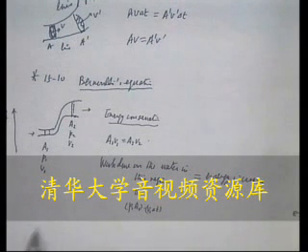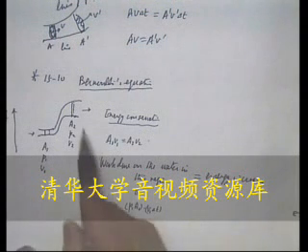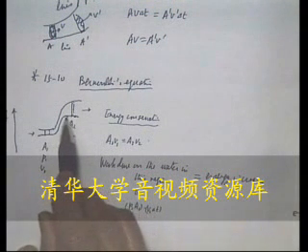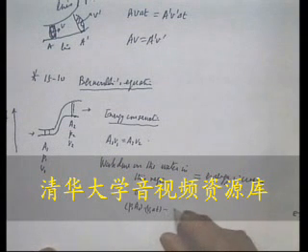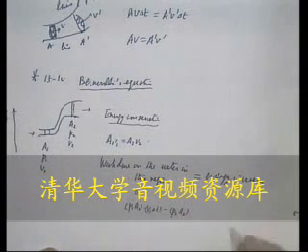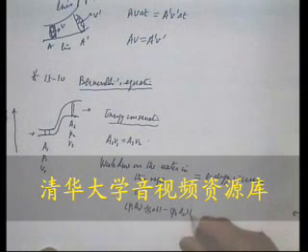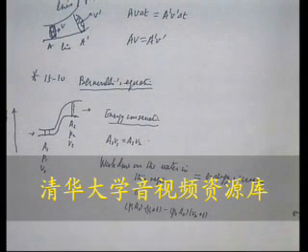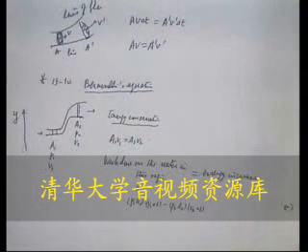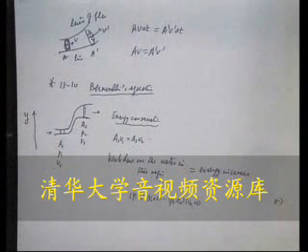This is the force done on the system. But at this point, the system does work on the outside. So therefore you have to subtract P2A2. P2A2 is the force times the distance traveled, it's V2 delta T. So this difference is the total work done on this system.